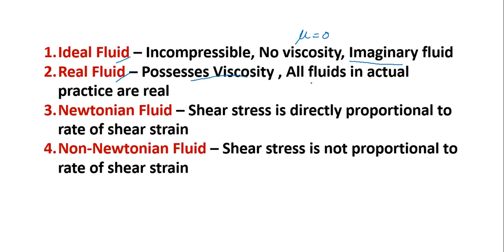All fluids in actual practice are real fluids. And Newtonian fluids are the ones in which shear stress is proportional to shear strain, and non-Newtonian fluids are those in which shear stress is not proportional to shear strain. These are the classification of fluids.